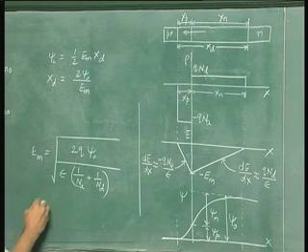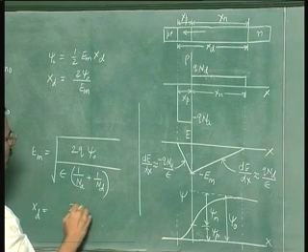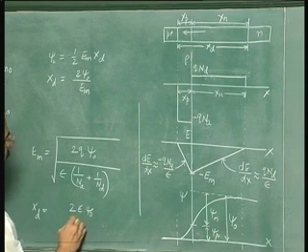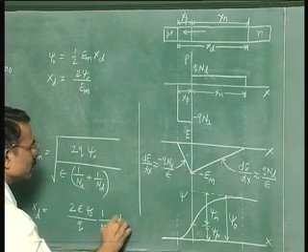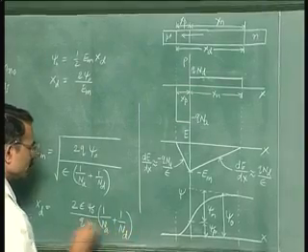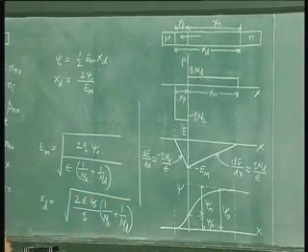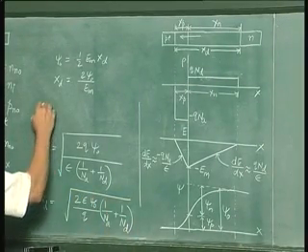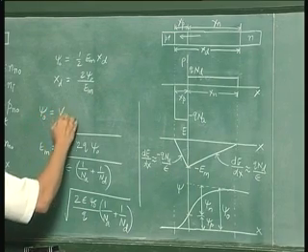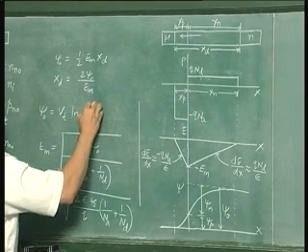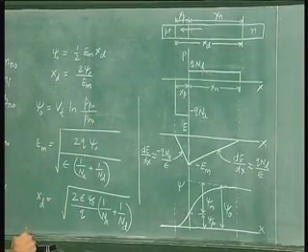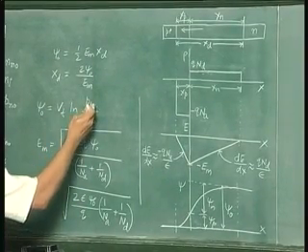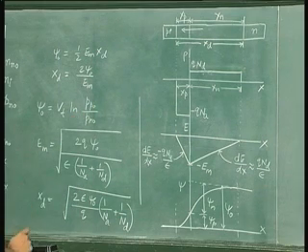So from these two you get xd is equal to 2 epsilon psi naught by q into 1 by Na plus 1 by Nd with a square root sign, where psi naught we have already determined is equal to Vt ln pp0 by pn0, or you could write in terms of nn0 by np0.